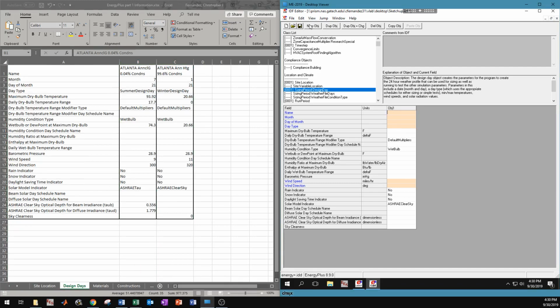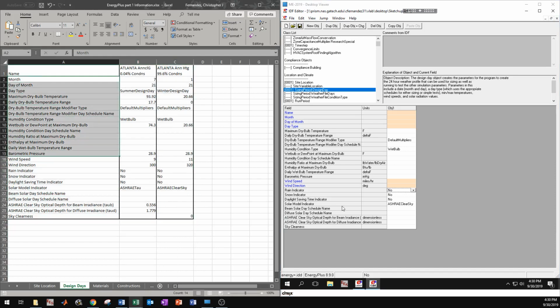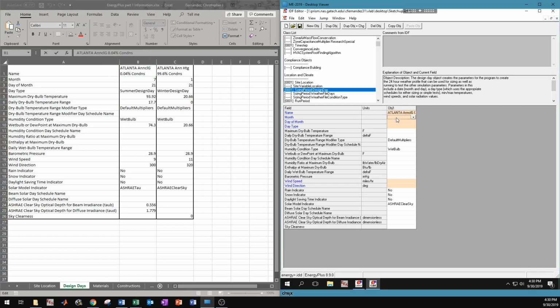That being said, sometimes when you create a new object, some things will already be added, and then this is laid out in the exact same way as this, line by line. So you can pretty much just copy things over if you want to. You can change names if you want to, but EnergyPlus is kind of weird because it has to be exactly the same for some things if it has to reference it somewhere else. And it also gets weird with spaces.